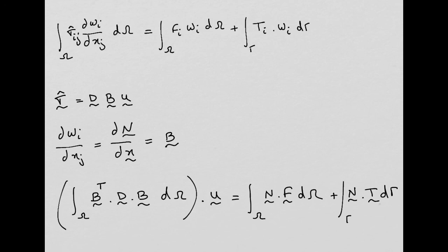When you use a finite element software package, you always hear about nodes, and you know the nodes is where you have the degrees of freedom, this U, right? These U variables here, they are at nodes. We are going to see then, not today, for different elements, how you define these degrees of freedom there, and how do you assemble the contribution to the global stiffness matrix of the stiffness of the individual finite elements? That's what I wanted to say.